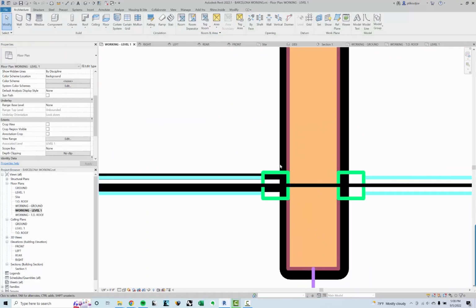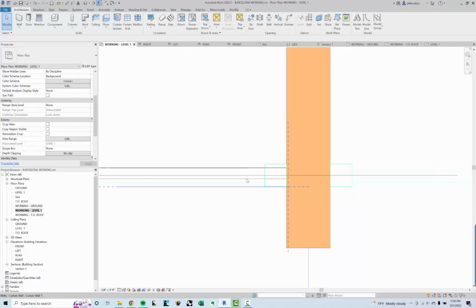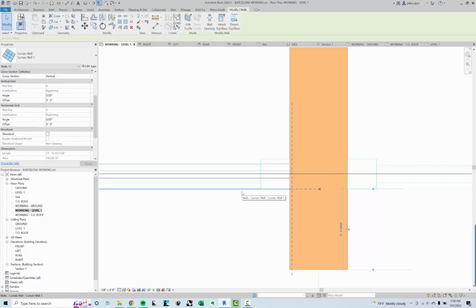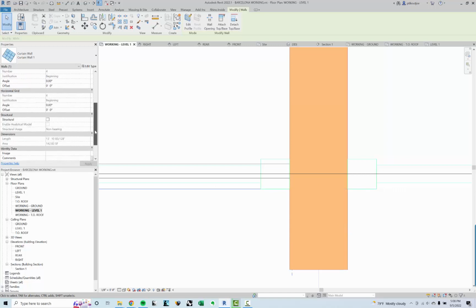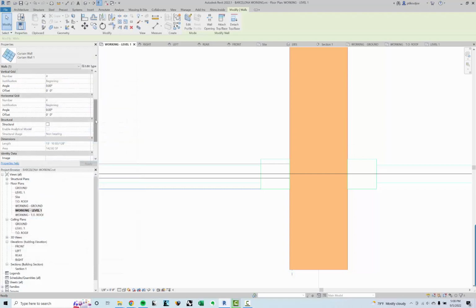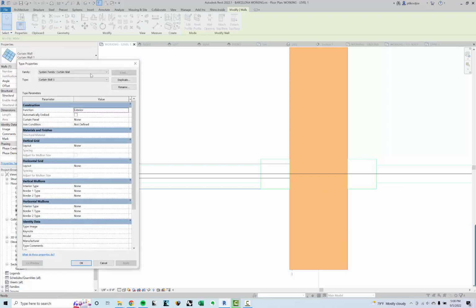One thing that you'll start to notice with some of this is that when the wall lines are thick, because what Revit does is it displays the print thickness. It's not like CAD where it's a super thin line. So you can start to get lost a little bit. If you click on this here, it actually will make everything more narrow. Now what's happening here is this offset, which is being dictated in the type. I'm sorry, the offset is here. Once we start adding mullions, we'll get this in the right place.